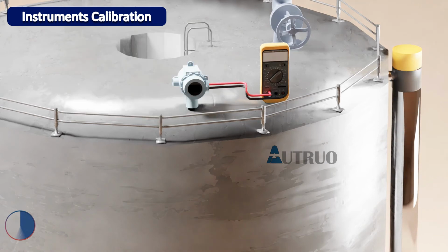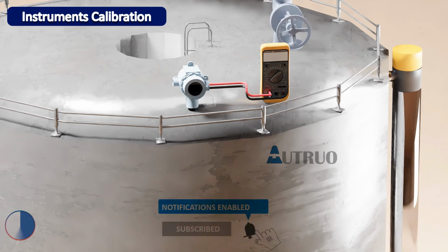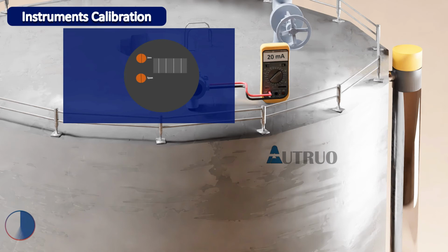Likewise, the tank will be filled to its maximum. A little glance at the sight glass is needed. Now that it has been confirmed physically, we will need to increase the span from 7.5 mA up until it has finished leveling up at 20 mA.